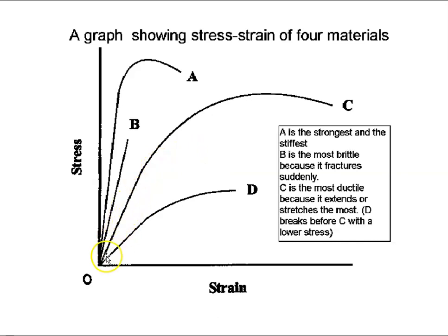So this one is creeping up, creeping up, creeping up. Permanent damage occurred, but it really lasted a long time after that permanent damage occurred, which is how we like buildings. We like things to creak and bend and give us warning so we get out of the building, basically. This doesn't give us any warning. This thing just shattered. Everything appeared to be fine, and then it just broke.